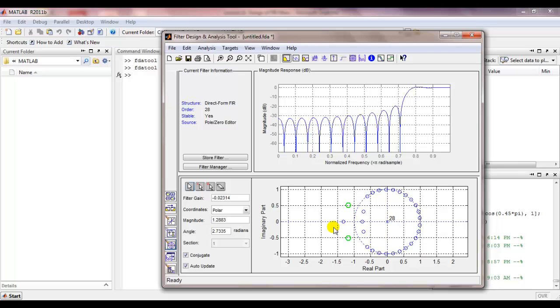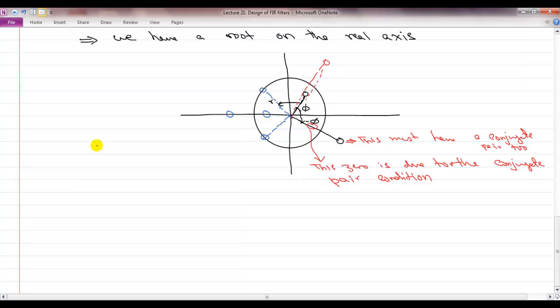Okay. So based upon this discussion, you can figure out that the impulse response of your filter is always going to have certain special shapes. And so based upon the length of the filter and the shape of the filter, you can characterize linear phase FIR filters into 4 classes or 4 types.